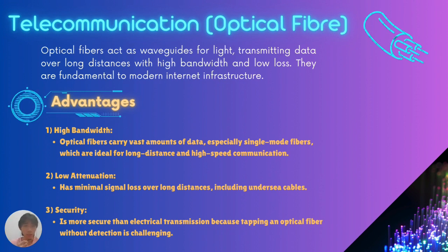And how about the advantages of using waveguides? Firstly, we know the waveguide provides a high bandwidth. They can carry a vast amount of data, especially single mode fibers, which are ideal for long distance and high speed communications. And next, they provide low attenuation. There is minimal signal loss over long distances, including undersea cables.